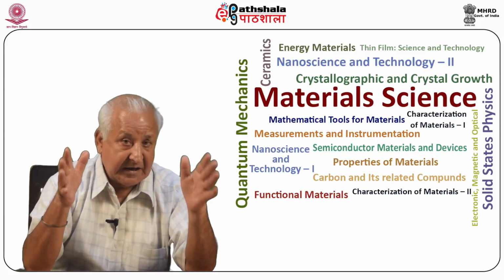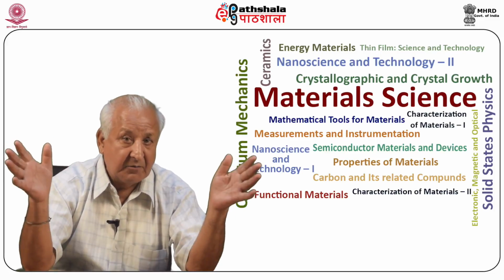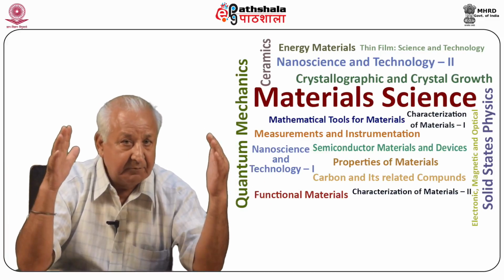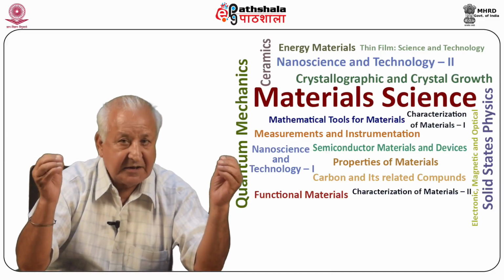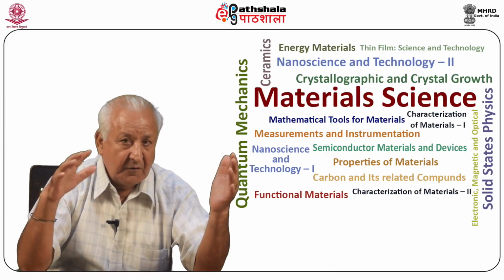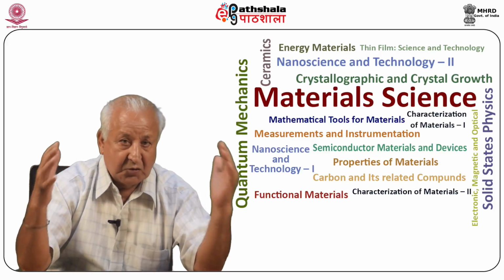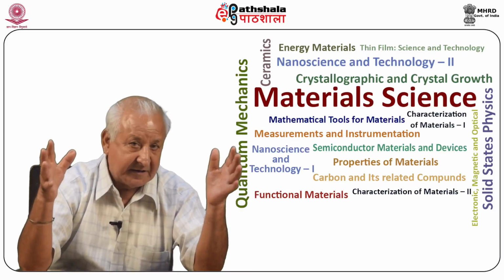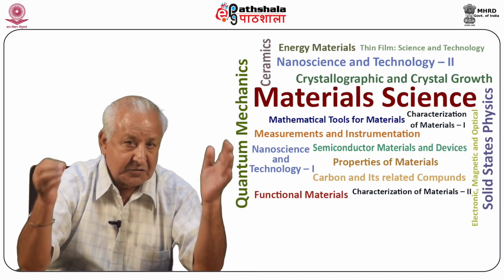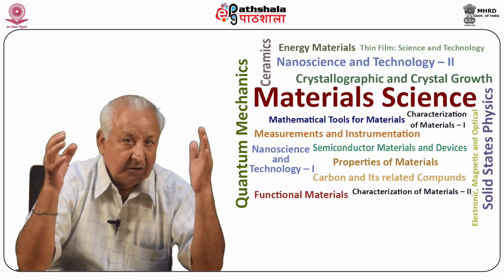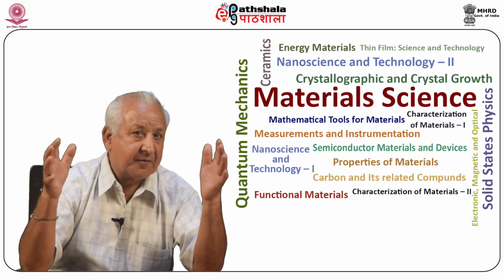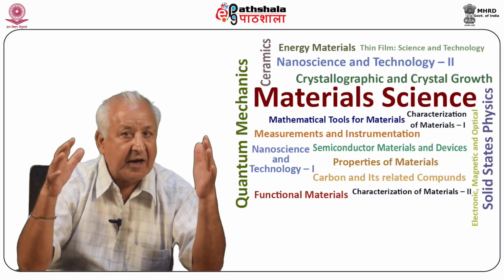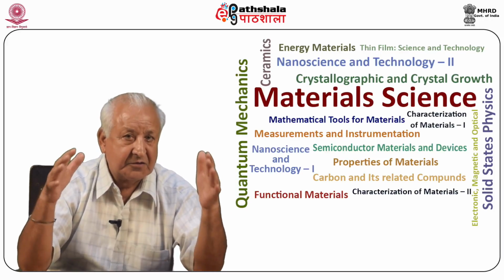At the equilibrium state, the material is completely molten above the melting point and completely solid below the melting point. As such, the transition of material from its molten state to solid state is quite fast at this equilibrium state. The problem for the crystal grower is therefore to control this rate of transition from molten state to solid state in order to ensure that single crystals grow.